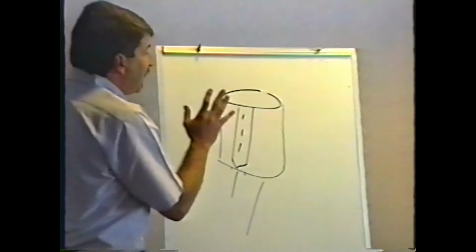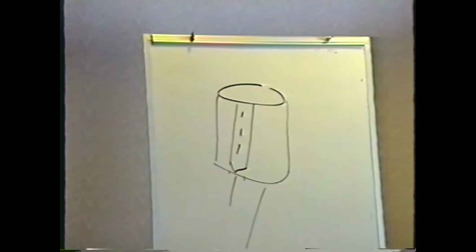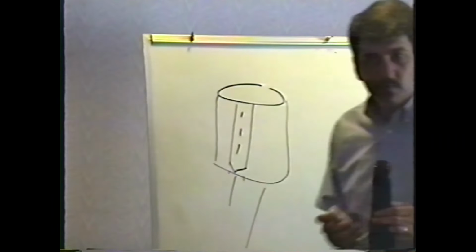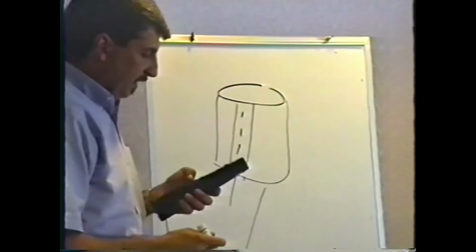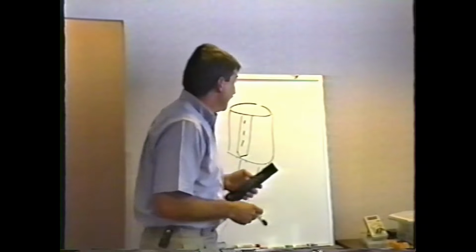That's so you can identify the capacitor from the bottom of the board. When you have it mounted on a board, you can look at the bottom and see which side's the positive end and negative end. And that's real important because if you connect the capacitor backwards, it will blow up. Not maybe, sometimes, kind of blows up, not blows up a little bit. It really blows up. It blows the heck up.